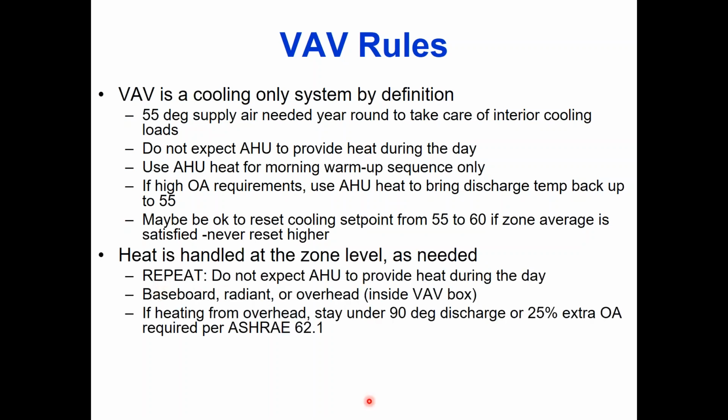If you do need heat, that's handled at the zone level. I repeat, the air handler does not provide heat in the daytime. Stop thinking that when you design it. If you need that, it's a different kind of design. We can help you with that. We can lay that out, but the zone layout will be completely different for that type of building. It will not be ducted anywhere remotely the same as a VAV system. So no heat from the air handler. The zone has to take care of the heat.